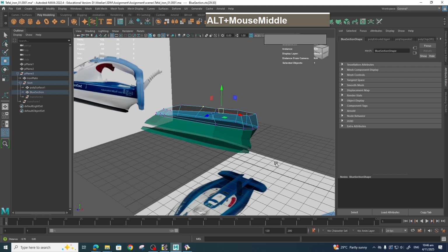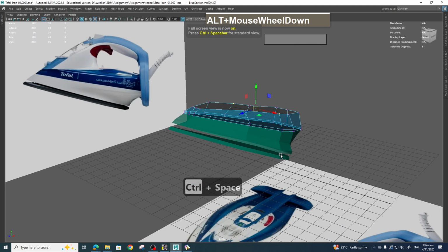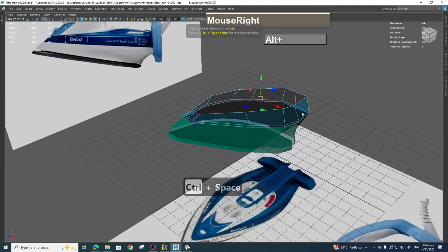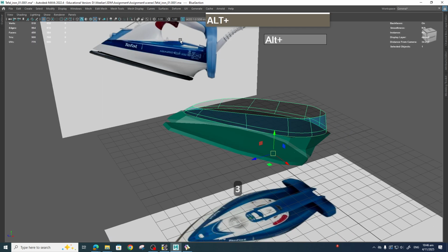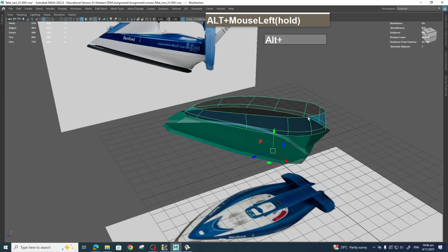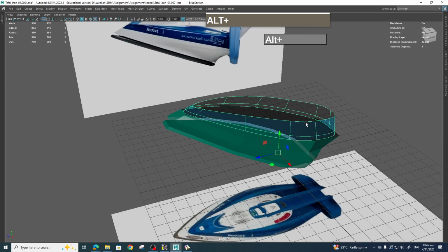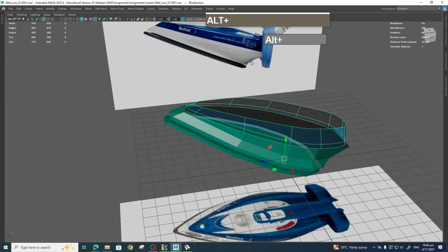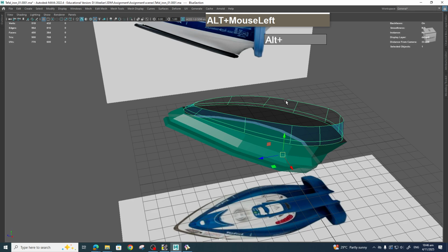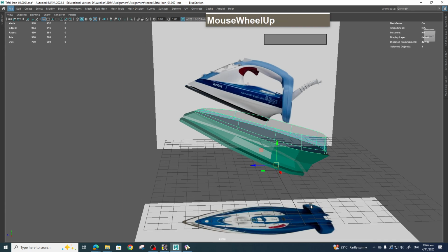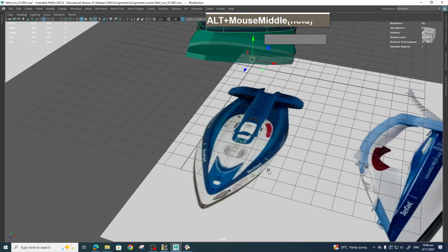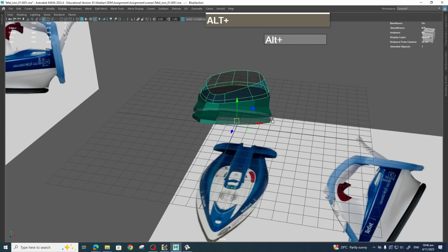Alright, so you can see the sections are coming along just fine. Press number 3 to subdivide this. This also looks quite okay. So now you can see this section here, it crosses over and then joins to the other part. So we can use the bridge section to bridge this section over. Later we will figure out how to cut the circular portion here for the levers and switch. So we can see from here, this curve over here.